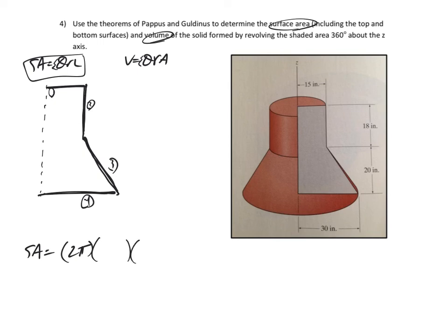The L is a little bit easier. The L, that's just 15 inches. So the R, what is the R? The R is the distance from the rotating axis, the perpendicular distance from the rotating axis to the centroid. Don't overthink that. It's just the centroid of a line is at the center, and so its R would be 7.5. All right, so that's the theta RL for 1.